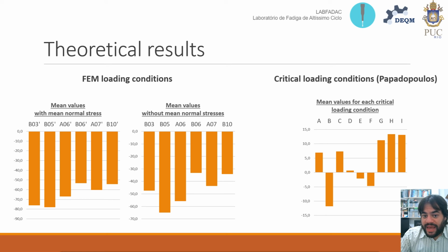As one could expect, for all loading conditions extracted from finite element analysis, whether fully reversed or in the presence of mean normal stresses, all the obtained error indices are very negative. This indicates that the crankshafts are not subjected to inadequate loadings, and the reported failures are very likely to be a consequence of metallurgical aspects.